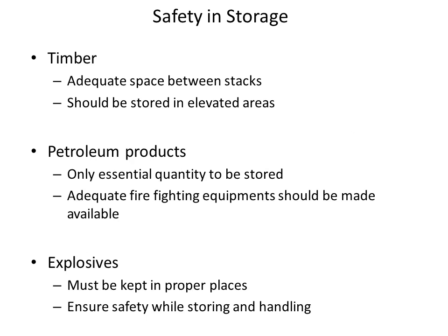Then comes the safety in storage. Here we are discussing the safety in storage of three materials, that is timber, petroleum as well as explosives. Timber includes sleepers, runners, etc. used in the construction field. In order to store it properly, we can stack it in bundles, and we have to keep proper distance between the stacks so that we have adequate ventilation and the chance of fire is prevented. Timber should also be stored in an elevated area so that we can safeguard it from water and so on.